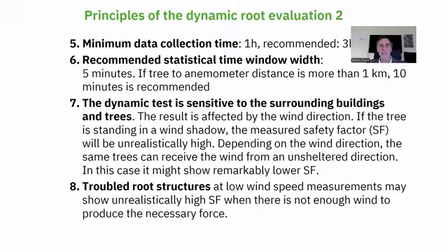The dynamic test is sensitive to the surrounding buildings and trees. Itself, this is a good message: we are closer to reality compared to the pulling test. The result is affected by the wind direction as well. If the tree is standing in a wind shadow, the measured safety factor will be unrealistically high.